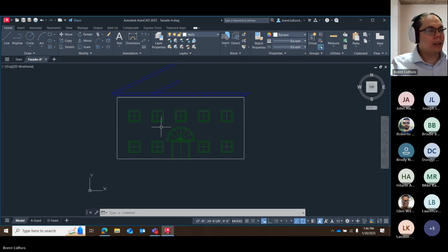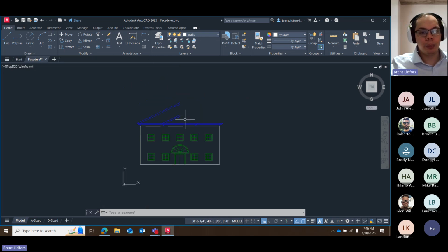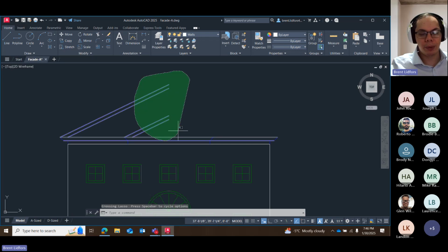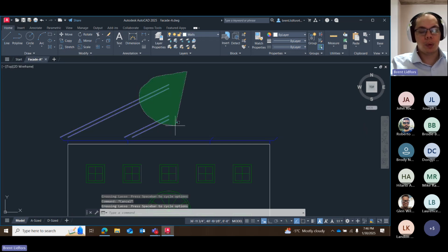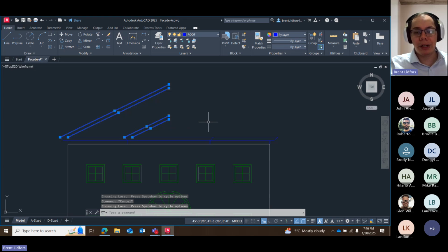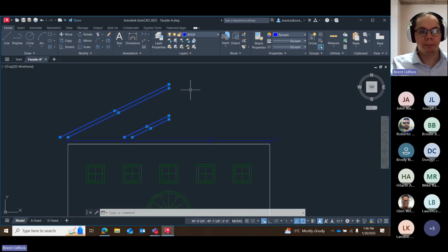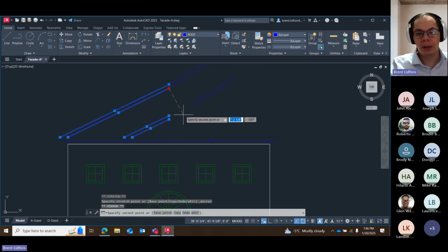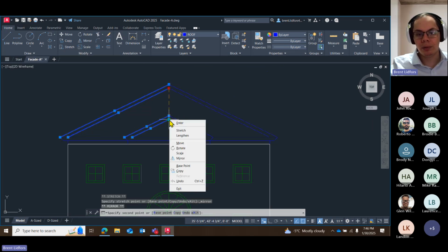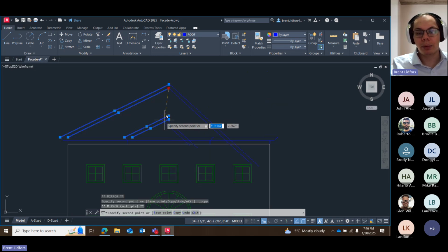From here, it wants me to use the angled lines of the roof. So the 4 angled lines up here, and I'm going to mirror and copy them so I have symmetrical roof lines up here. So I'm going to use mirror by clicking on any hot grip. Any of these 4 end ones will work. Choosing mirror and then making my line of symmetry. I'll also right click and select copy so it keeps my original intact for when I mirror.